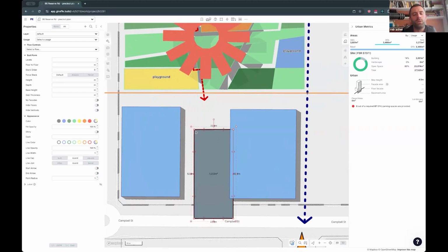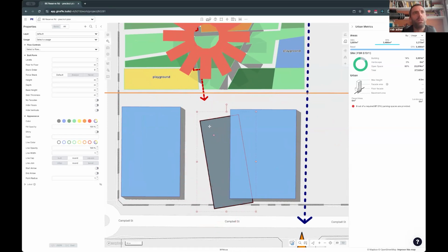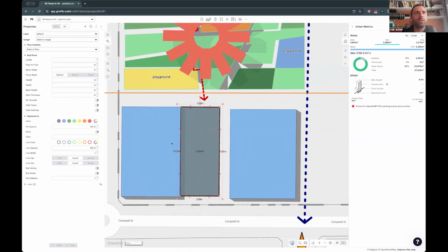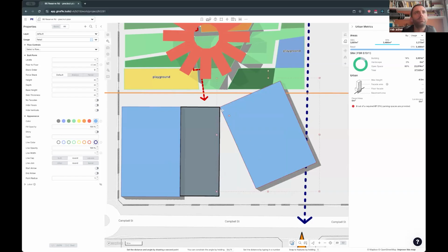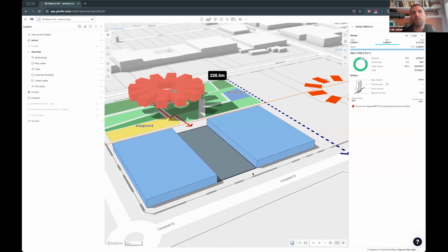Probably the biggest one is just the B key. So if I hit the B key, I go to the base point mode, the base point move mode. And so what I did there was I tapped B, I held S to snap, and then I completed my snap. And if I hit Shift B, I'm in base point rotate. So now I can snap this geometry to that geometry precisely. And I can repeat that operation over here and rotate it out, rotate it back, whatever I want to do to draw precisely. So now we know that those 2 points are touching exactly.